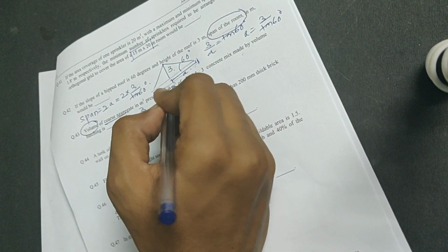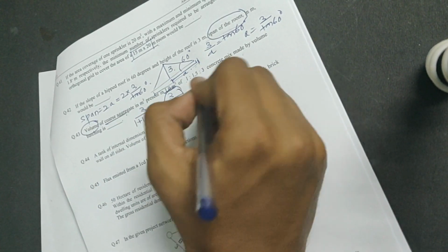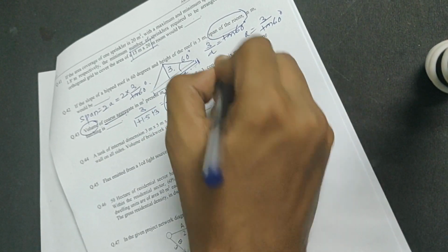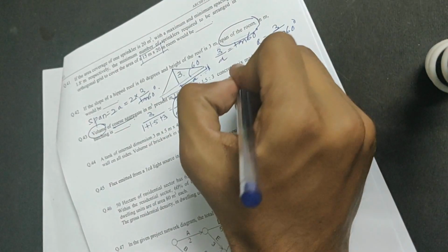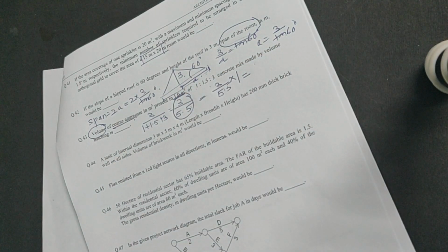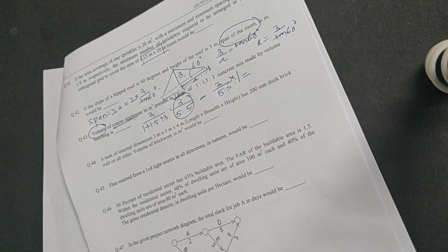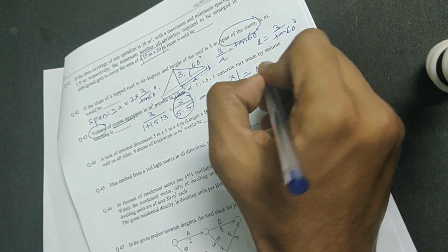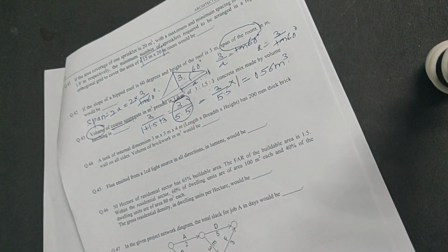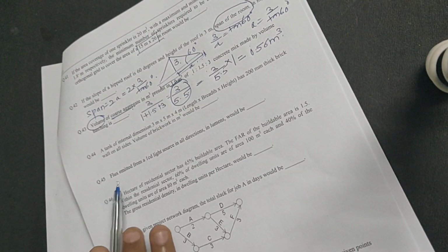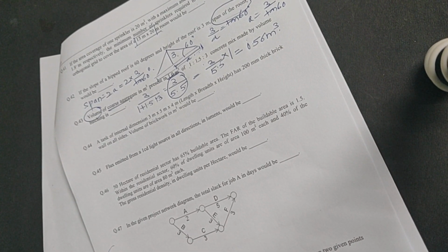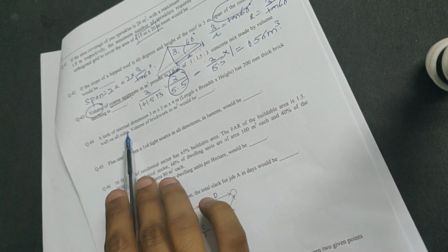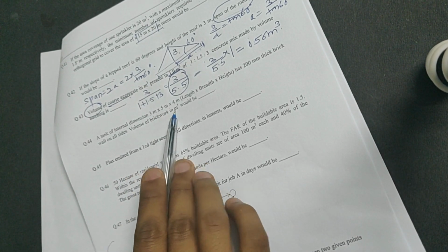So this is basically the proportion of your coarse aggregate. We have to find out the volume of coarse aggregate in 1 meter cube. So it would be 3 upon 5.5 into 1, the proportion out of 1. So the answer is 0.556 meter cube to be exact. This is how we do it. Again, the next question. Some questions are really easy and some need a bit more. Sorry for that, I just slipped. Next question is, a tank has internal dimensions of 3 into 5 into 4 meters,